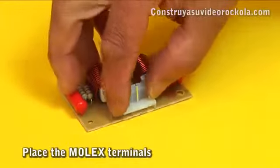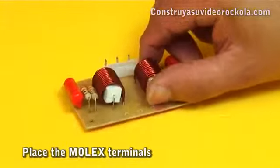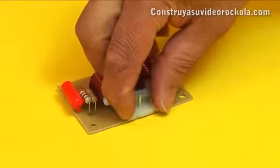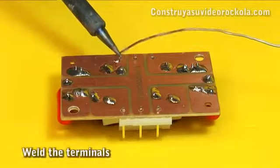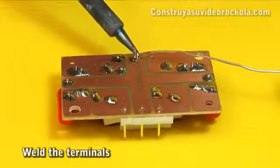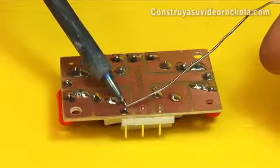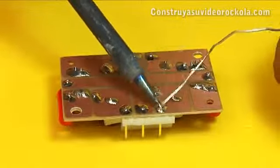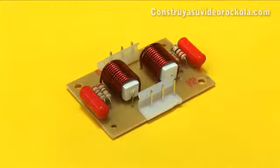Now, place the 6-pin Molex type terminals, from which we have previously removed the pin in between, and in the opposite direction, so that when installing the circuit, it can only be connected in one direction. Finally, we solder the terminals to the PCB. The solder should be plentiful, and perfectly surround each pin. We have ready our Zobel network, which we can use with a great variety of amplifiers.